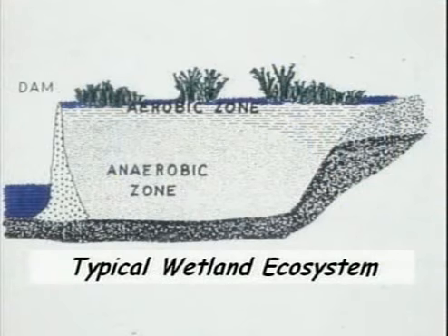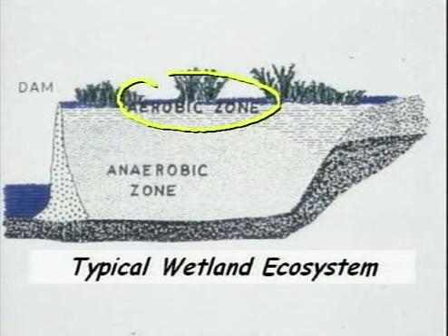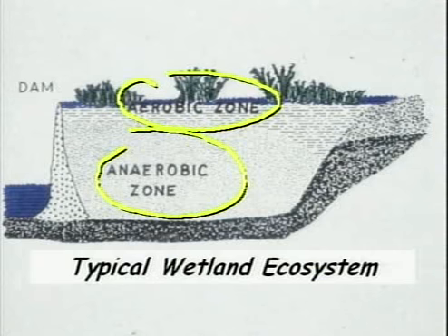Geochemically, there are two zones that form in a natural wetland ecosystem. The aerobic zone, near the surface, where oxidizing reactions like iron hydrolysis occur, and the anaerobic zone beneath it that is dominated by reducing reactions like sulfate reduction. These naturally occurring geochemical zones compete against each other, and a given horizon may switch from one zone to the other if the water levels fluctuate. Thus, metal precipitates that may have formed could actually be redissolved and remobilized when the geochemical conditions are varied.